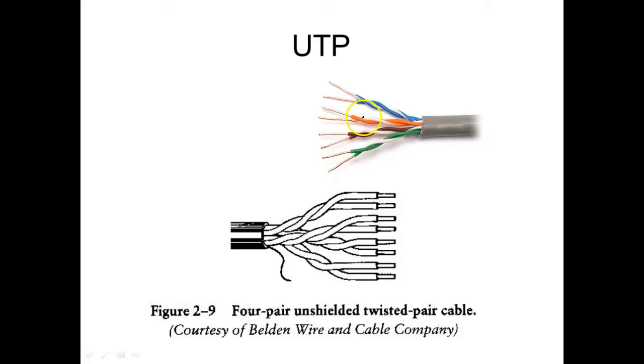If you had unwound it, or you were working on somebody else's that was unwound, you don't know how many winds to get it back right. What if you cut back to the good wire and then count them? You could do that per inch. That's what you're shooting for, so many twists per inch. So you could get it close. It would probably be better than leaving it untwisted, in my opinion. Are we okay?